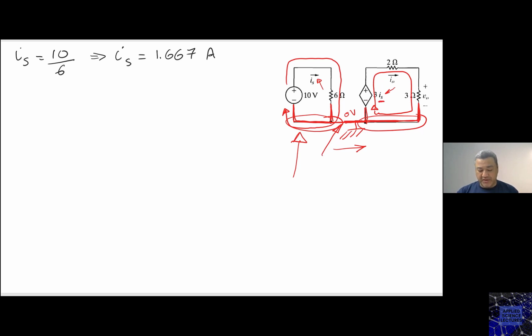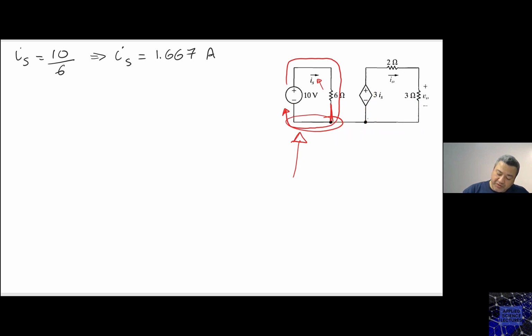Now, tell me what's going to happen. So let me ask you this. Let me now clean up this whole thing. Now we understood what happened. But let me ask you this. What's going to happen if I come and break this circuit? It's just one mesh or loop here. What's going to happen to IS? It's going to remain constant because it's only going through that loop.